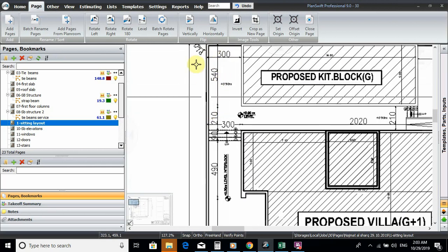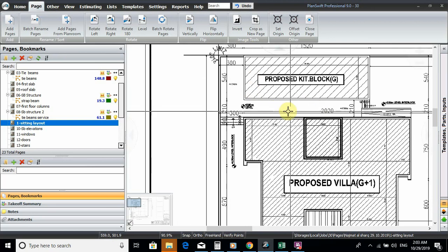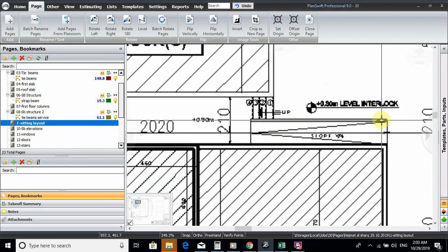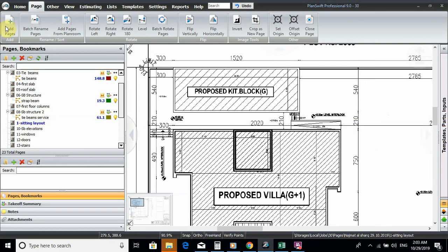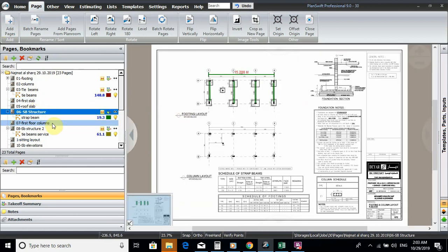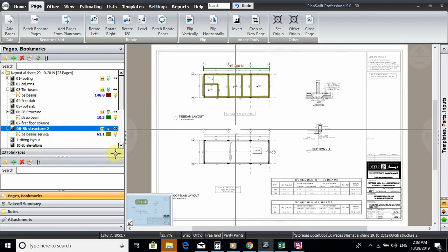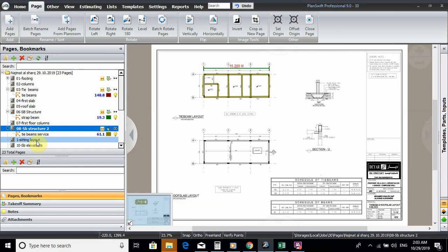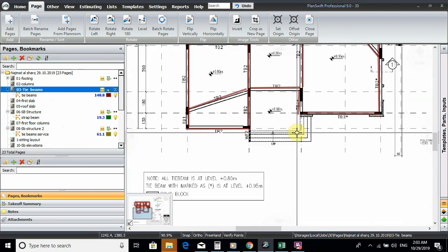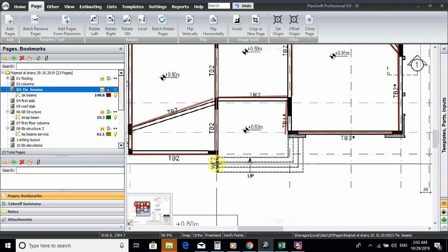And the backfilling here will be surrounded by the boundary wall tie beam. So you don't need wall footing to hold the backfill. You may need a little bit here, but you don't need it also because he already didn't write it down. So forget about it if it's not mentioned. Okay, but just tell me in a comment. Hey, this is like this. Just send me a comment. I will study it. No problem. Okay. Only here, WF2.